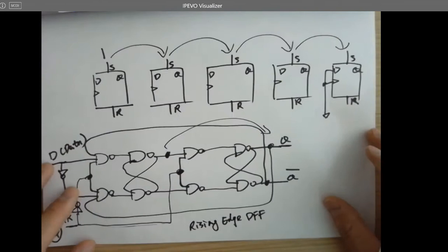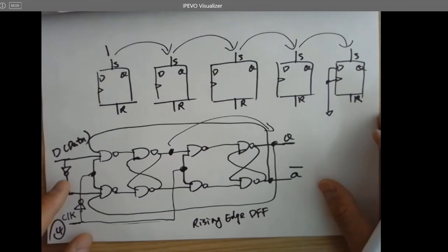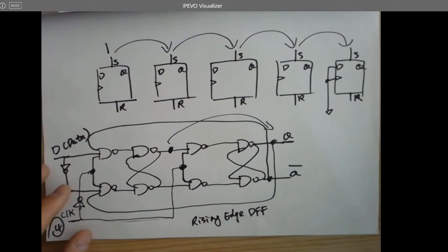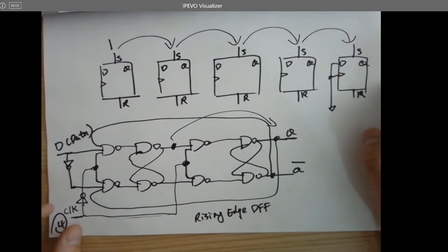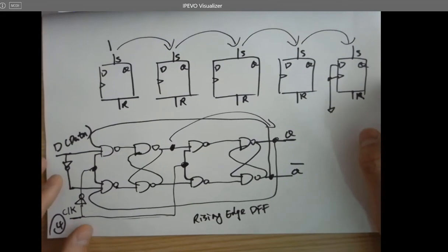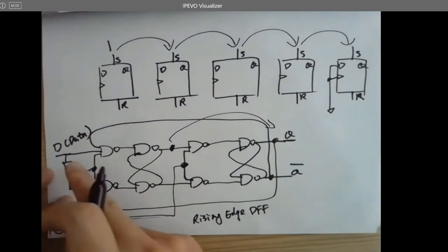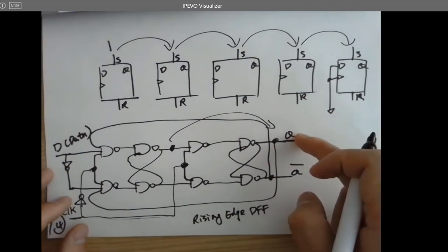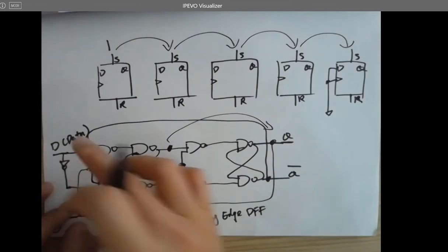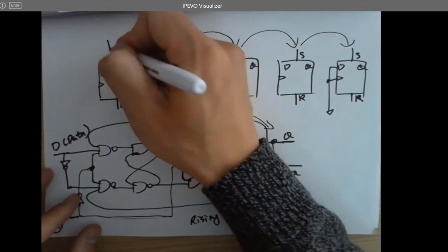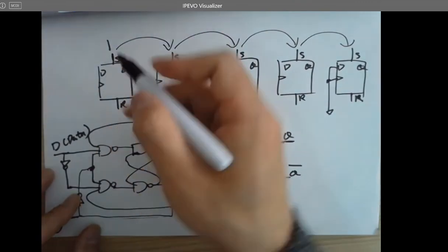So now here's the question. How can you set and reset Q? Which means I have a little bit more control over the output, which is Q. If I give a signal, I can set the D flip-flop, which means it's not being controlled by the input signal anymore. If I set it, Q is going to be 1 no matter what the input is, right? That means it's a set function. Set. That's a pin. That's S, right? It's not 1S. This is a pin.